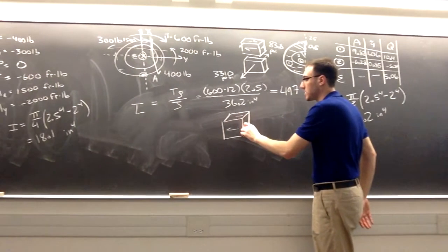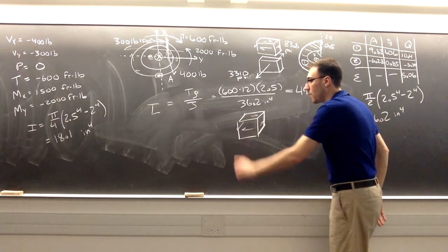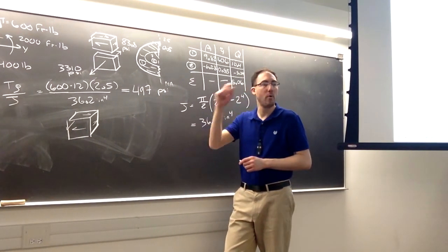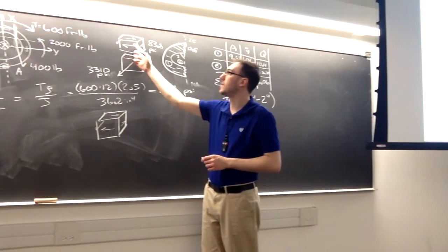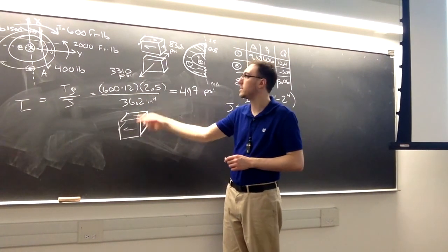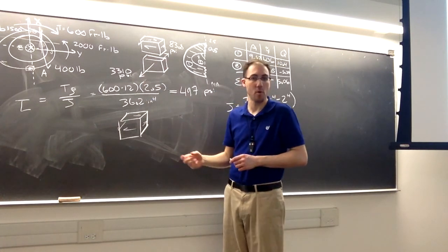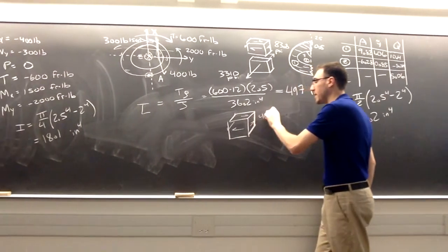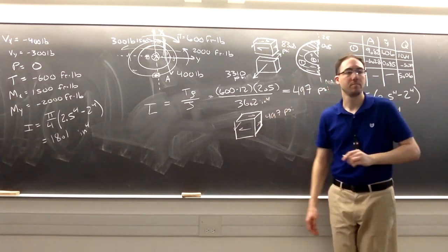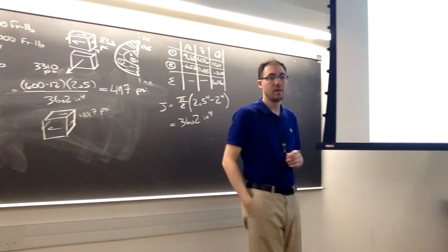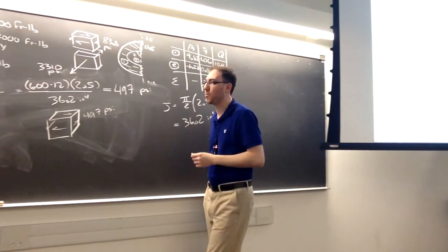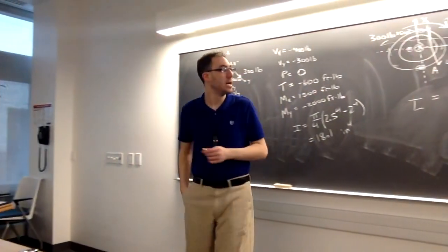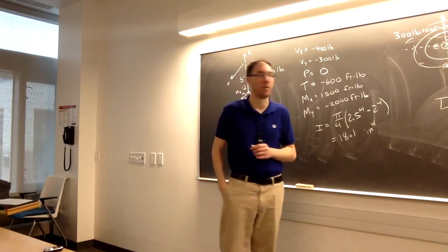And like we saw in the last one, where we had shear stress, we have to balance that out to make the full stress state. So at point A, it is pointing in the same direction. The shear stress points in the same direction as it did due to the shear force. That's not always the case, though. And this has a value of 497 psi. There was no internal pressure. We didn't have to worry about that. So we've accounted for all of the things that cause stress at point A. It turned out there were 3 things that caused stress at point A.